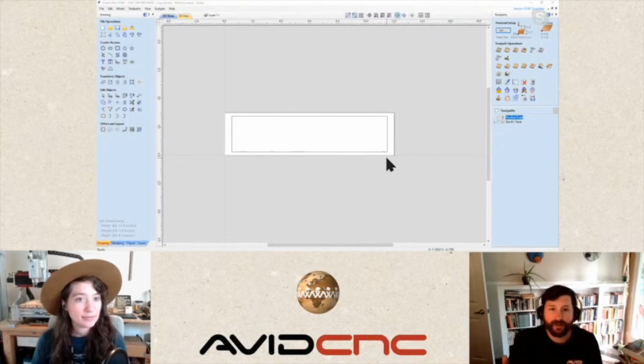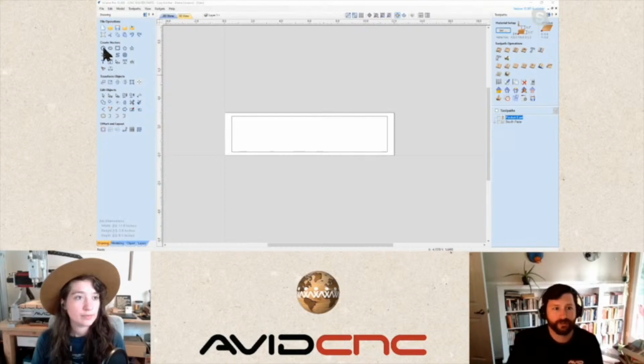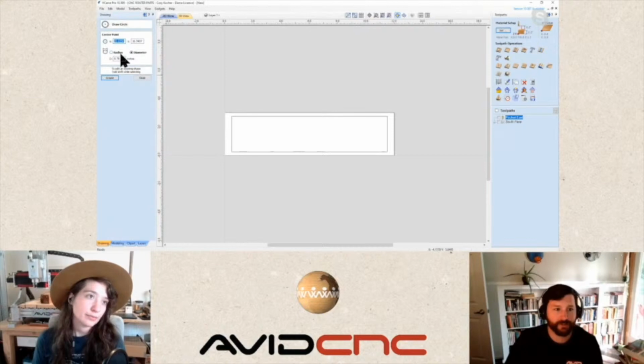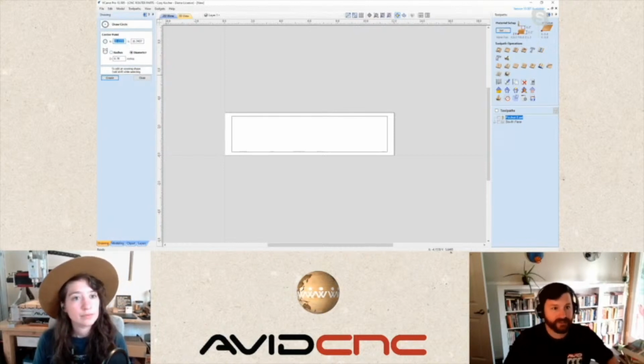All right, well, let's talk about making a counter bore in this material. There's a couple different approaches we can take. Again, I'm going to really try as best as I can to do more milling than drilling. So let's go ahead and put a starting point of X 3 with a diameter of 0.375, and Y 1.5. There we go. That looks closer to the center of our material.